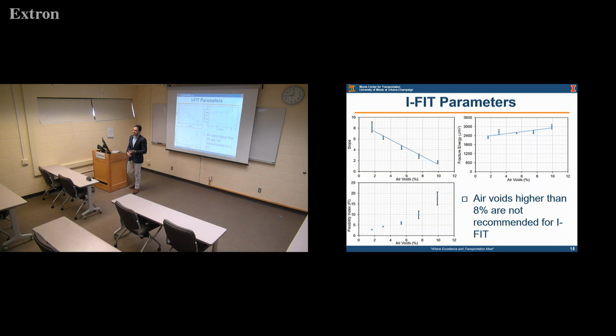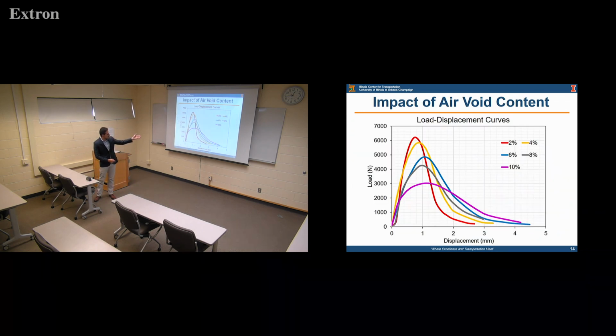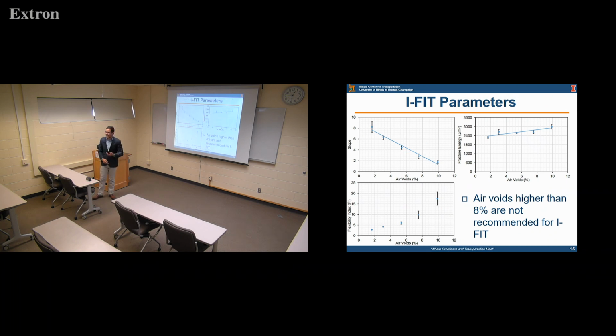When we see the iFit parameter, the iFit result, we see the same behavior. When I increase the air void content, the slope that you can see graphically here decreases. And that decrease in the slope causes an increase in the flexibility index.